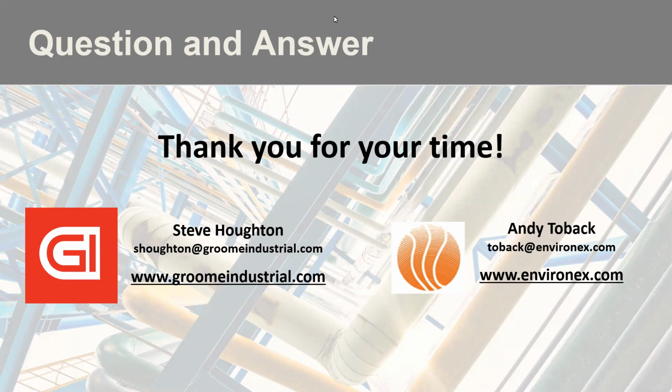based on your ammonia flow rate. And then you would, in this case, need to know what your inlet NOx is. And then obviously what the stack NOx is. So then you would have a ratio of your inlet ammonia to how much of your NOx you converted across the SCR catalyst. So that's a measure that Environex routinely performs when working with plants to project catalyst life or determine where a unit's at in terms of benefits of tuning.